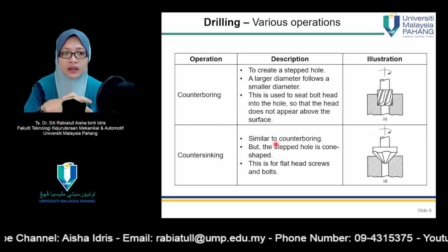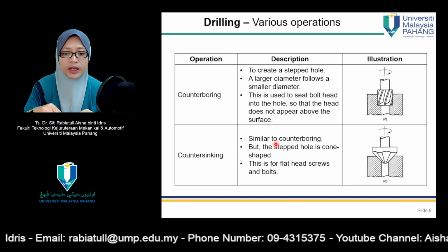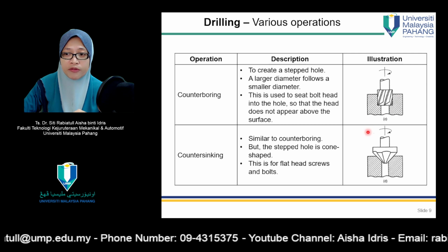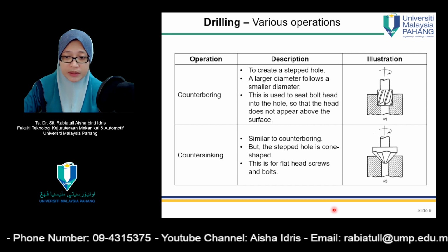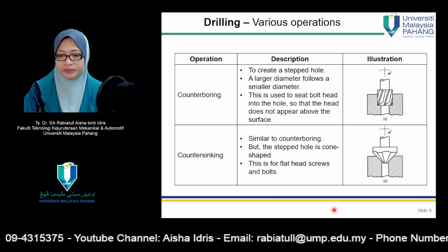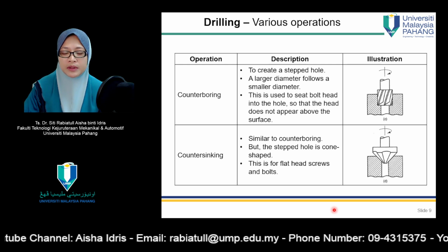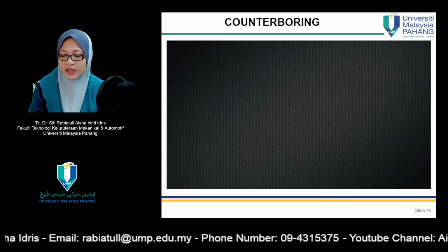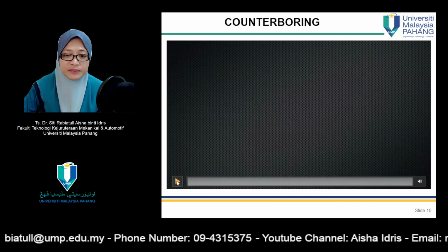Other than that, counter boring. Counter boring is a process of creating a hole in a hole with a larger diameter, as you can see in this illustration, in this figure over here. So that is counter boring. Counter sinking, the process is the same as counter boring, but the hole that is created is cone shaped. So we are going to need other types of screw head for such a hole. So let's look at a video for counter boring, how it is being conducted.